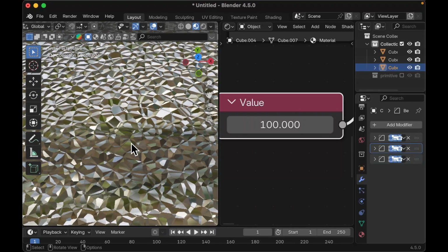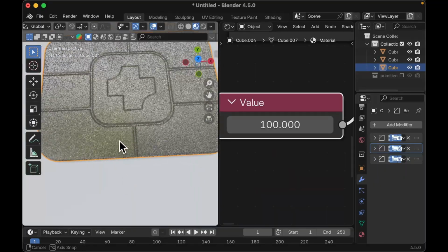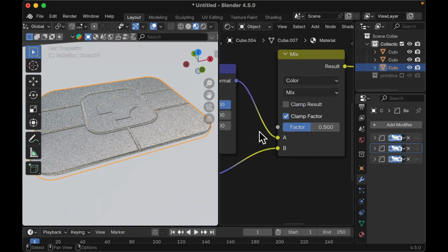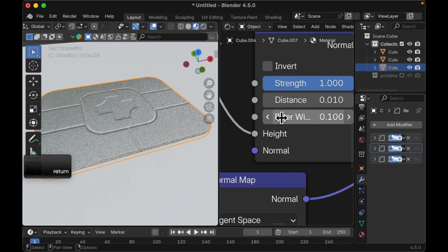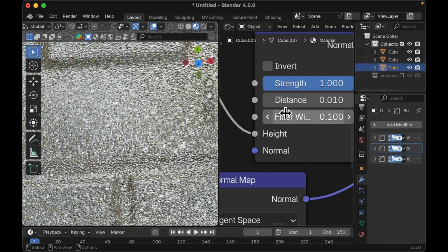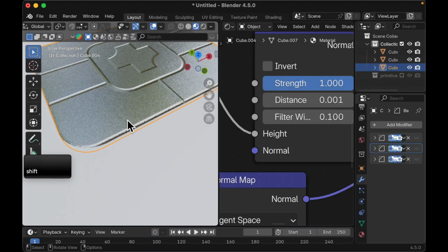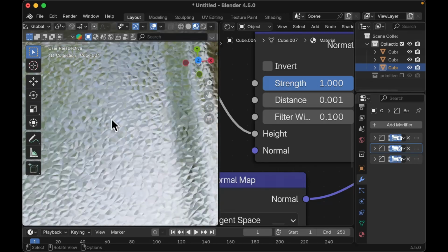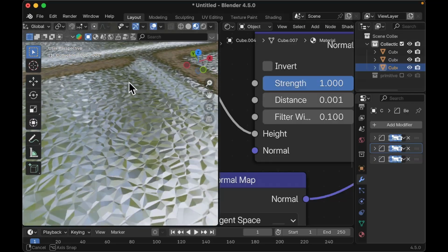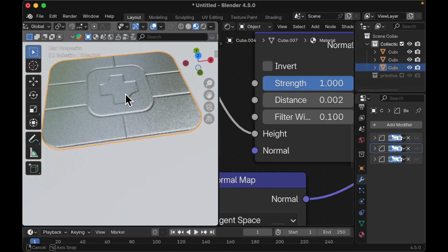Then I enter 100. So at 100 inputs, you have this very sharp crystallizing surface. That might be too much, so you need to bump down your distance. So I can add a 0 here, see how it feels. If it still doesn't work, I'm still going to add 0 to it. You can always tweak these things. All of this detail will matter when you're trying to render, because it's going to be the difference between a crispy, glittery image and just a flat surface. So you can always zoom in to see how much of this change you want. So I can say 0.15, see how that goes. And then we have that done there.